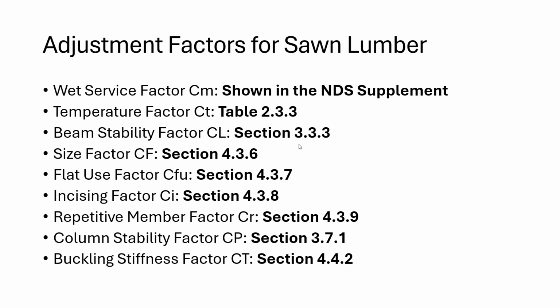And you can experience a large reduction in the design value from this. So you can't really just leave it at 1.0. You have to work it out, and you'll get a feel for the effective length, and then what your other factors are and how they're going to play a role in the stability factor. And you could probably get a feel for it and then guess, hey, this is going to be pretty close to a 0.95 reduction. So I'll go ahead and do that without having to run all of these formulas.